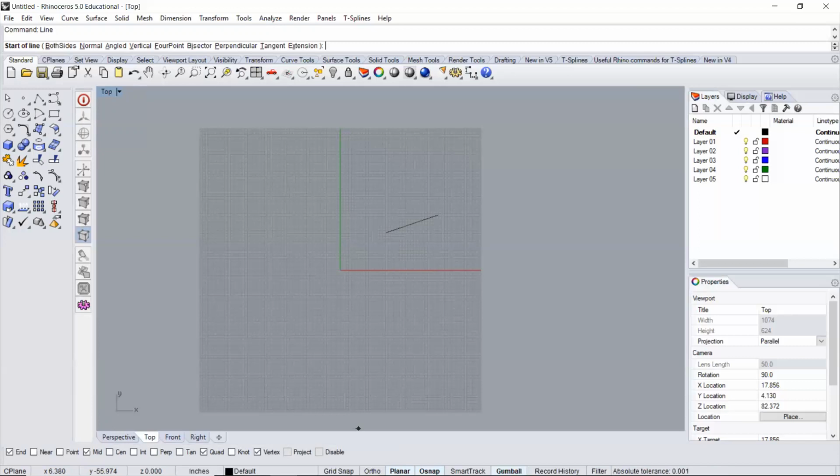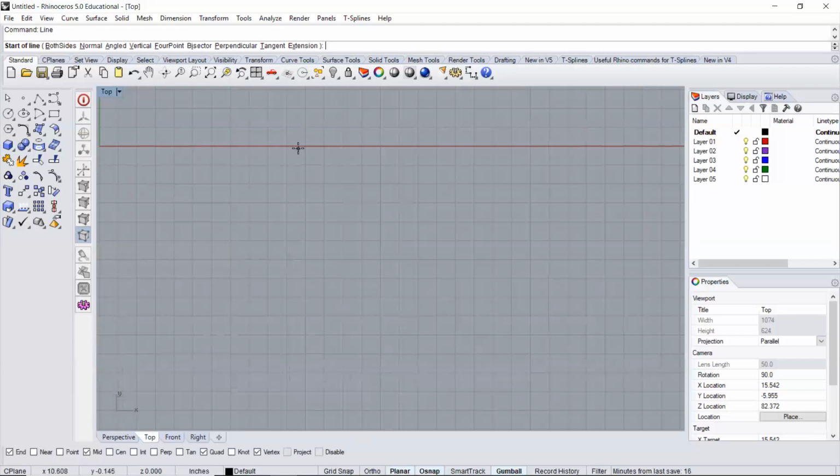One of these options in the PC version says O snap, and that means object snaps. So as I toggle that switch on and off, I can even see how it grays out my object snaps. Some of the others in here that can be helpful are things like grid snap. If I want to take advantage of the grid on my screen, I can turn on grid snap and my cursor will follow along with my grid lines.